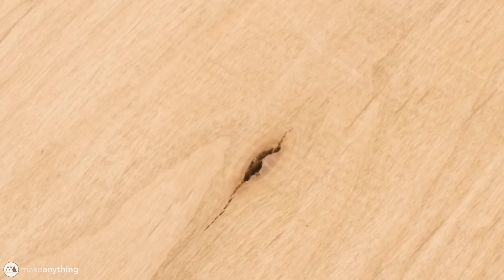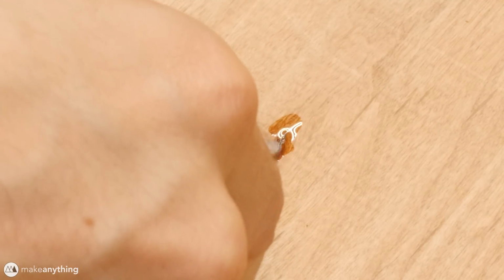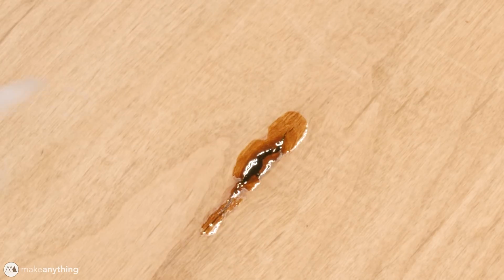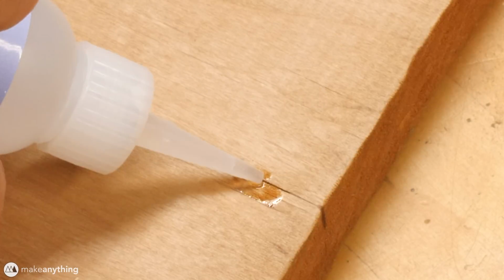After cutting the pieces of wood down, I am going to want to plane the pieces so that they're all nice and flat and the same thickness. But before I got to that, I noticed several cracks in my wood. And to prevent them from expanding, I'm going to fill them with some of the thin Starbond glue, which really seeps in all those cracks.